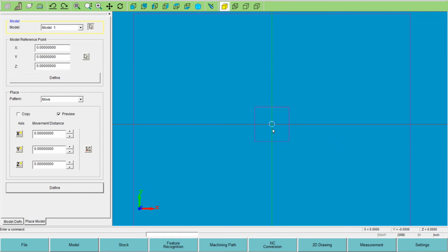So why did I do that? This had a circle there. It seems like we could use a circle. Circles are geometry that you can maybe wire cut, and start holes are for the tool path to start from for your lead-in line. So there are two unique differences between them. Both are circles, yes, but we need to define a start hole to be able to make a machining path, a tool path. Okay, so we have that ready to go.